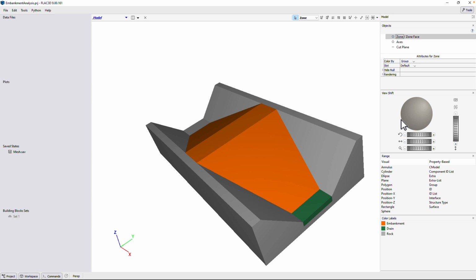A similar set of data files as in previous analyses were used. 1_static analysis, in which the total stresses of the dry embankment are computed. 2_seepage analysis, in which the pore water pressures are computed with the reservoir. And 3_update stresses, in which the effective stresses and densities are updated. Note that for this relatively simple mesh, the flow through the drain was not explicitly modeled, and therefore the computation of water flow in 3_flow calculations was omitted.